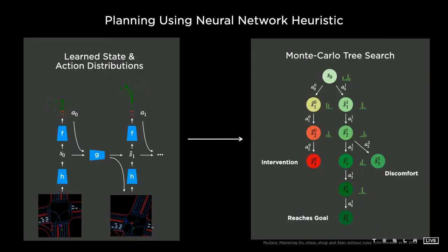We can design more and more of these heuristics to help the search go faster and faster, but it's really tedious and hard to design a globally optimal heuristic. Even if you had a distance function from the cones that guided the search, this would only be effective for the single cone, but what we need is a global value function. So instead, what we want to use is neural networks to give this heuristic for us.